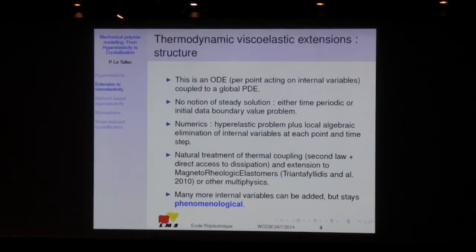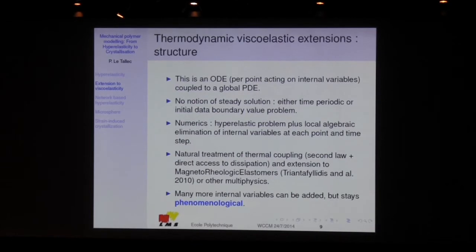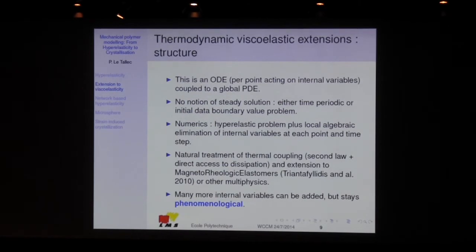From the numerical point of view, the strategy used more generally, that we favor in particular, is to use time discretization of the problem and a local elimination, because of the constitutive law of differential equation, the local elimination of the internal variable, so that you can reduce the problem to a hyperelastic problem after this algebraic local elimination.